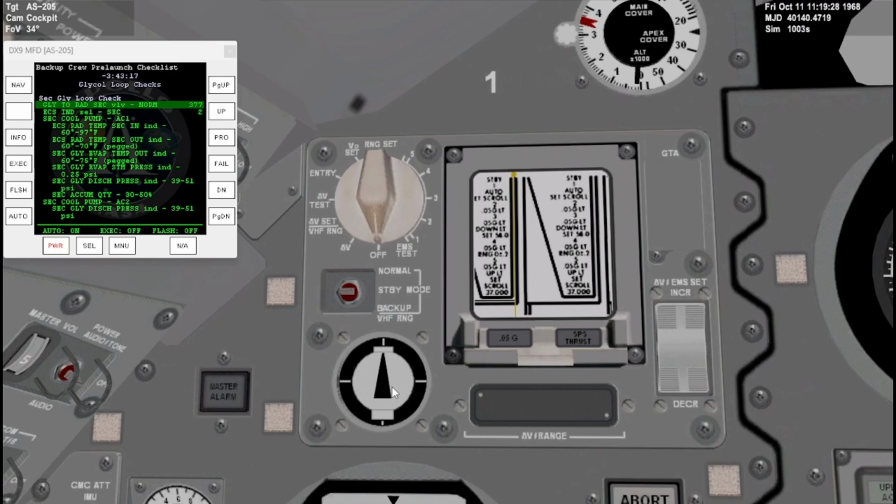This is our lift vector indicator with EMS roll on. This will monitor our roll and yaw through and will adjust accordingly. Lift vector up means we will pull out of the atmosphere. We'll take a more shallow approach with less G's, but we run the risk of skipping out if we're from